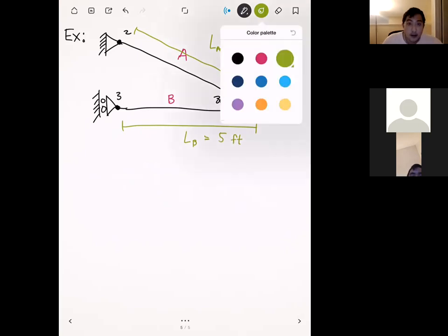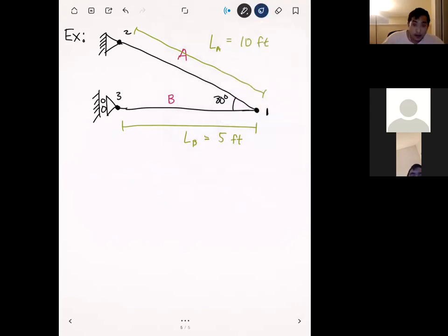And so let's define the Young's modulus and the cross-sectional area for both of the beams. Both beams are going to be identical in terms of that. Both beams, or both trusses. My mind's kind of getting ahead of myself already. Let's say both elements have the Young's modulus, we'll say it's 30 times 10 to the 6 psi. And then the area will be 1 square inch.